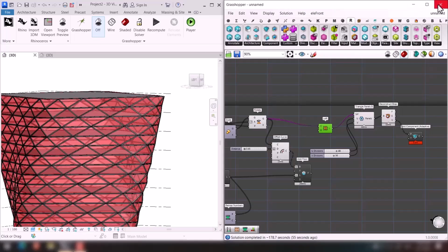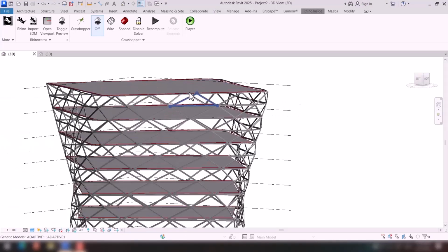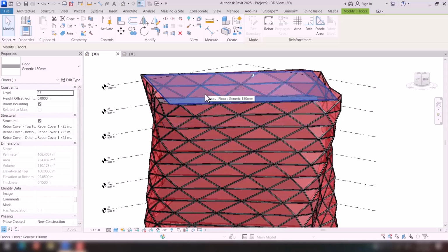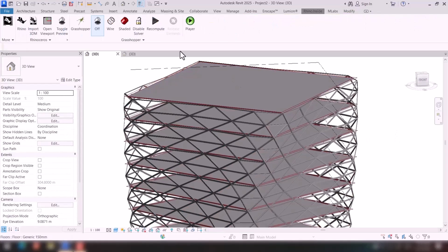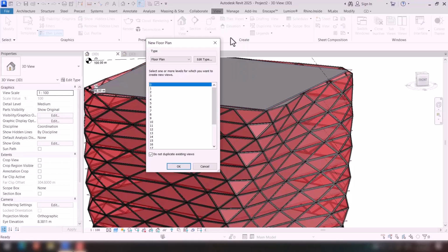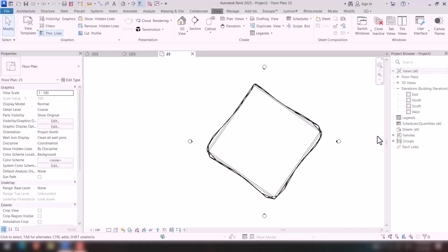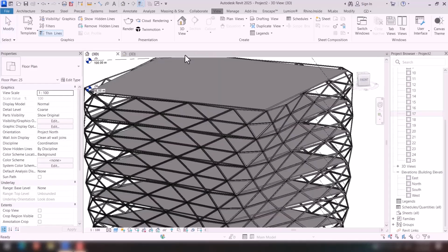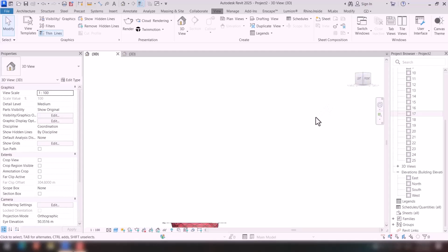And we can always continue our work in Revit, guys. So it's better to say we can always continue working on the created items in Revit. To give you a demonstration on this, I can select something here, then unpin it. Then, for example, change up the type. And as for another thing, from view, floor plans, I'm going to select all the levels and add them to our project browser. Just to get them as a list of levels in project browser. Yeah, simply done, guys.